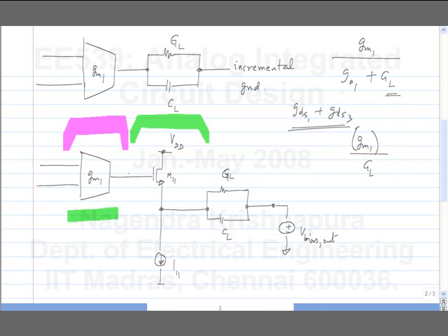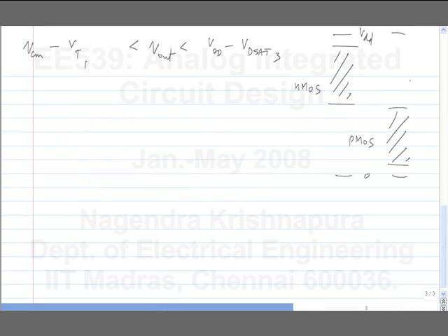So, what is the output swing limit of this? The whole thing minus Vt. If we assume no body effect, the entire swing limit gets translated by Vt, isn't it? I mean, sorry, not Vt, Vt plus Vdsat, the VGS of the source follower. So it will be something like this. So this kind of thing is okay.